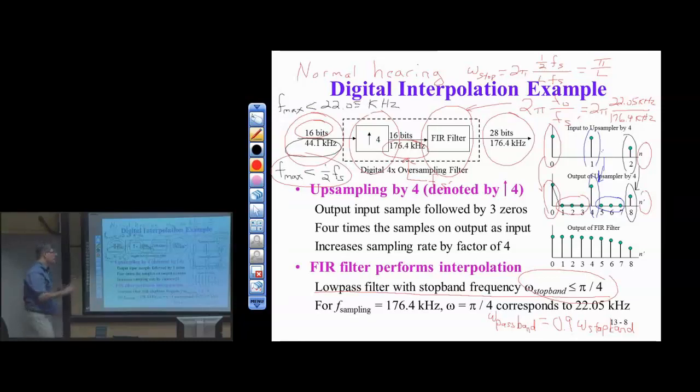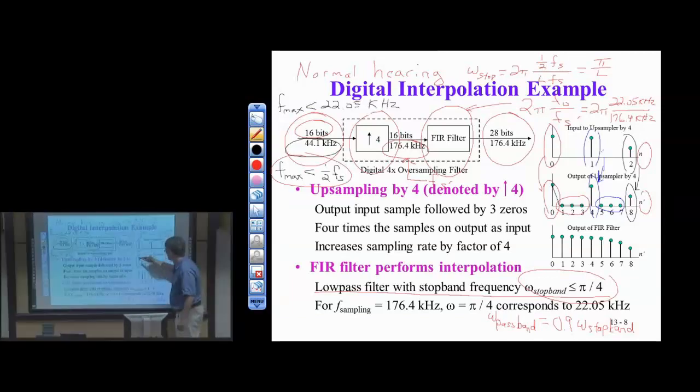Okay, so I've given you the story in the time domain and the frequency domain. After the FIR filter is applied, we'd like to connect the dots, the samples that we started with prior to upsampling. The FIR filter essentially will filter the samples we know, which are shown here. Those are the samples we know. You have the zeros inserted between them, or after each one, however you want to look at it. And our FIR filter now will try to connect the dots that we know, shown here in green, to get a smooth output. So now we've filtered, we've made this signal smoother.